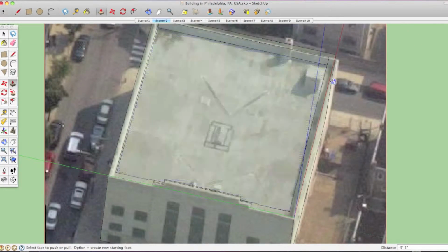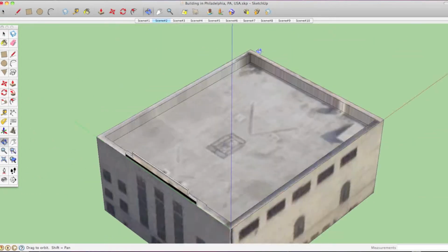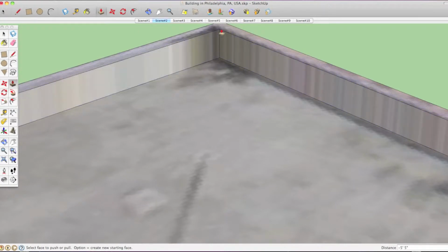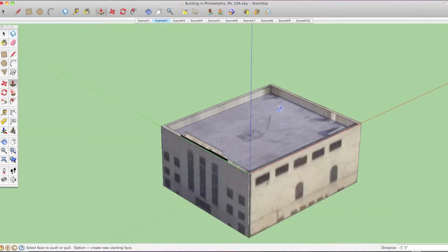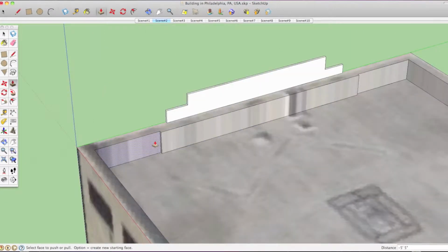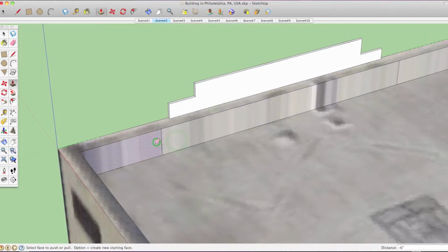So we'll drag it down. So as you can see, that gives us sort of a nicer look. It's not perfect, but what it's doing is selecting these lines of pixels and just drawing them down as we push-pull down. And that actually makes it look better. I noticed that I actually had selected this gable as well, but it can be easily remedied. Push-pull.